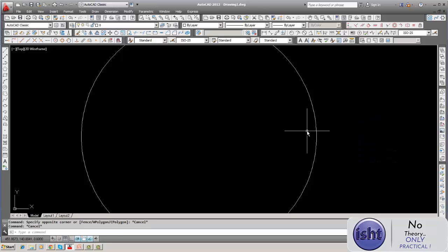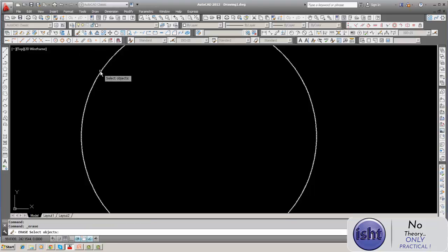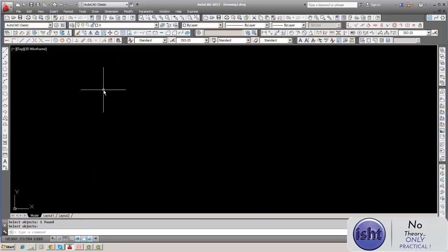In the case of a rectangle, both the sides will be increased. That is, suppose a 50 mm length will be increased to 100, and a 25 mm width becomes 50. So the area is increased by scale squared, because it is length into breadth. Similarly, the area of a circle is also increased. This is how we can increase or reduce the scale.